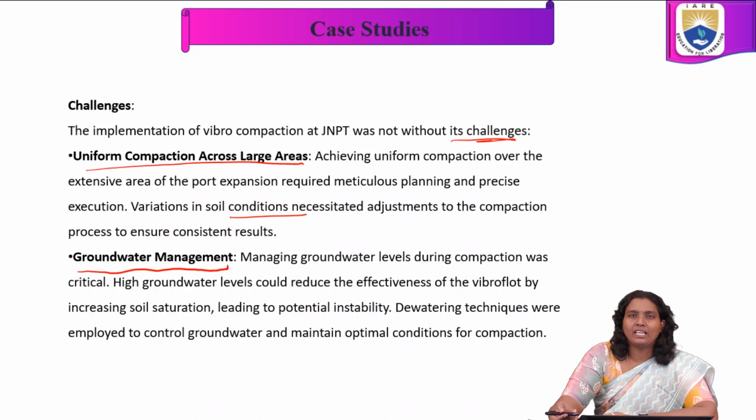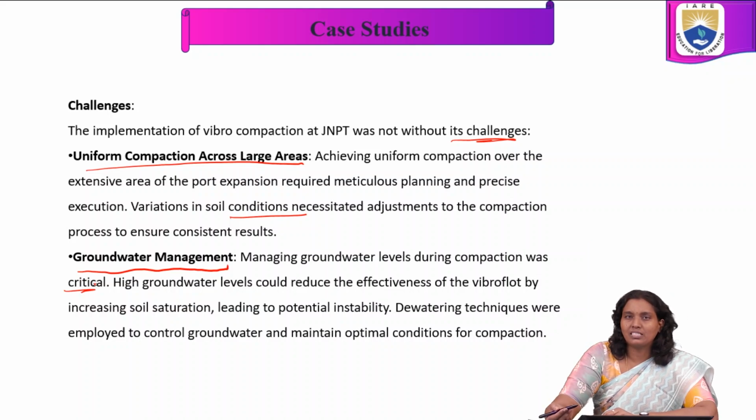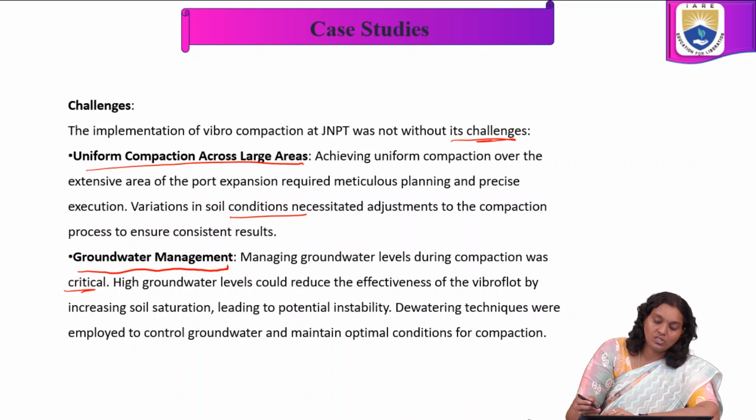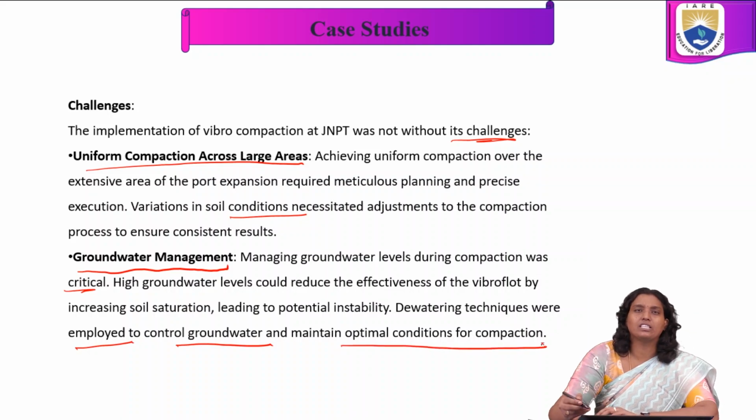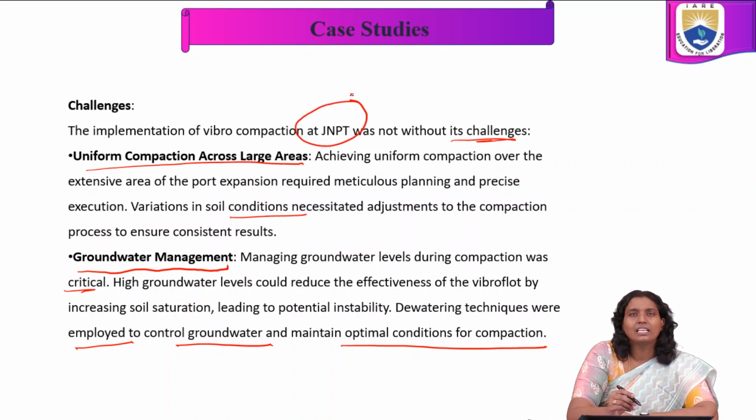In groundwater management, managing groundwater levels during compaction was critical. High groundwater level could reduce the effectiveness of the vibroflot by increasing soil saturation, leading to potential instability. Dewatering techniques were employed to control groundwater and maintain optimal conditions for compaction. So these are the challenges we had to overcome at the time of implementation of Vibro Compaction in this particular case study.